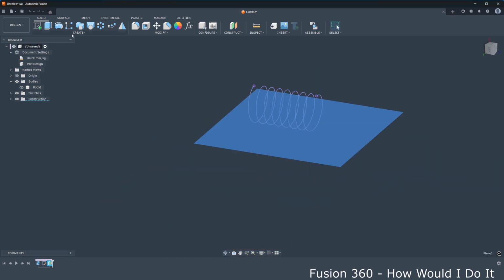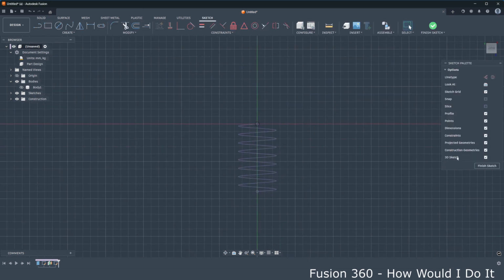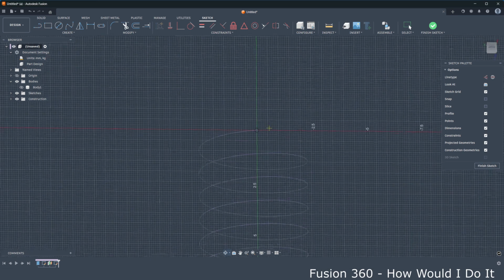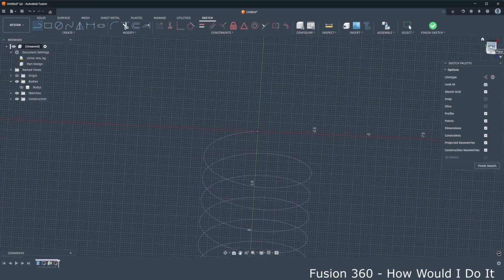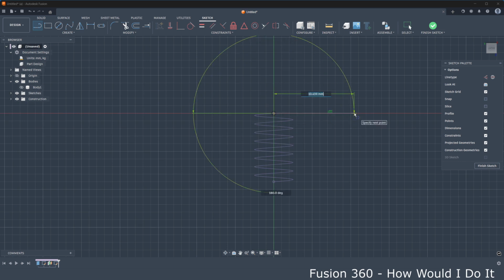Now in this plane we will create sketch. We will first uncheck this 3D sketch. We don't need 3D sketch anymore, so we will uncheck that, and we will create line. We have this point here, as you see, this point. I will go back to this view, and we will have this line 10 millimeters, and one more line like this, 8 millimeters. Enter.